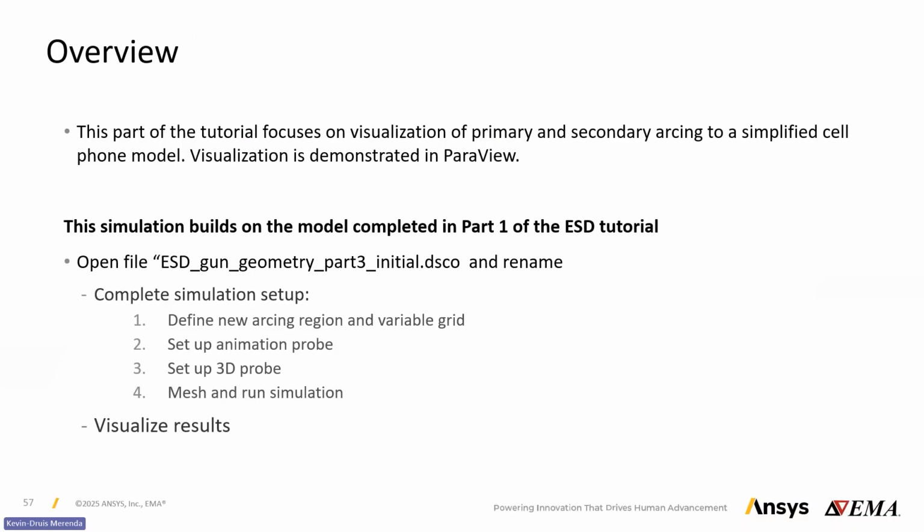So here we really want to look at that 3D probe in a lot of detail. We want to be able to manipulate where the ESD happens very easily and be able to remesh the simulation quickly and change the settings of basically the gap size that we're applying into our system.